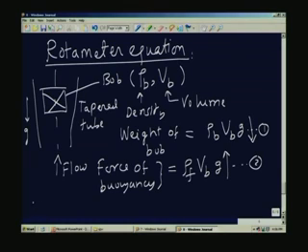Okay. There is a third force which we called the drag force, and most certainly it is not due to viscous effects. It is only due to the shape, the way the flow negotiates the body, and therefore is mostly due to the form of the object. Therefore it is called the form drag.